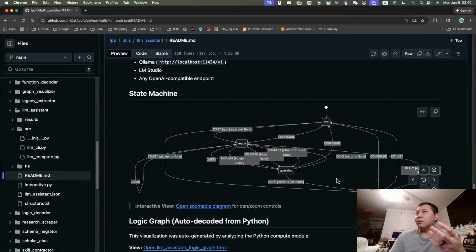It is like when I was in chemical engineering, right? You want to have certain control. You want to have your pressure valve somewhere, a gauge somewhere, you can test your pressure, and you can exert control before and after the valve. You can have a bypass as a maintenance bypass and things like that.